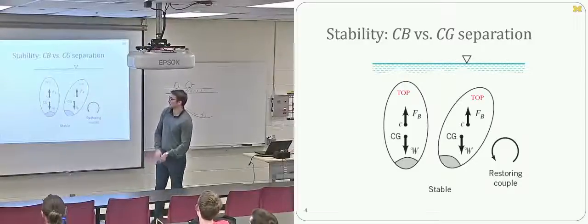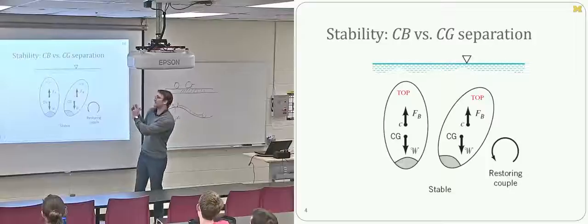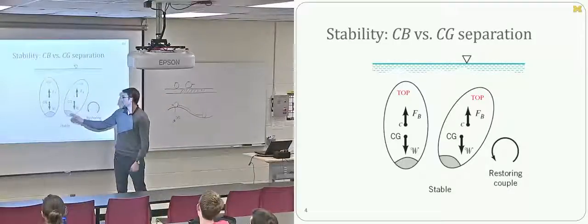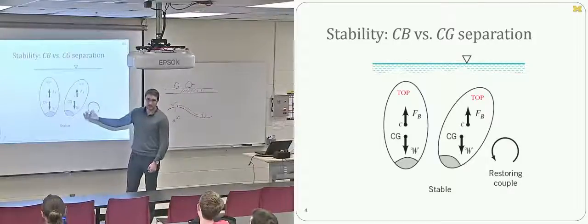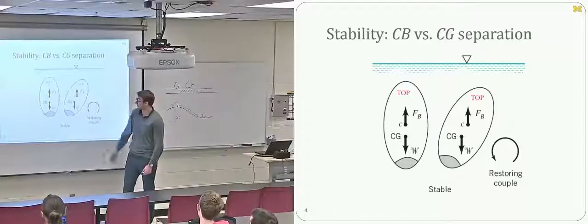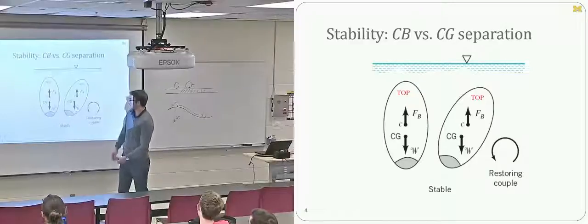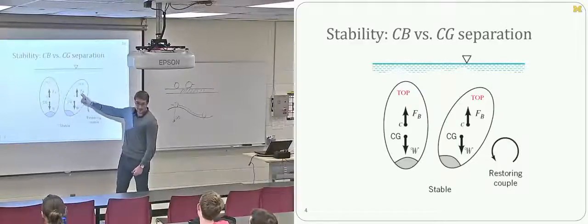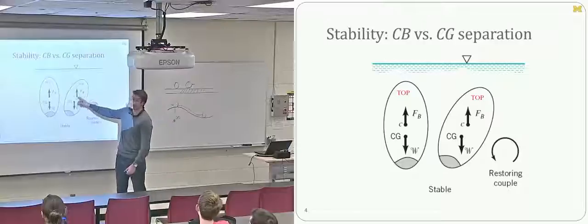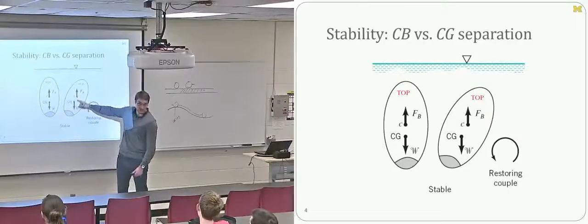The idea here being that, for example, if you took that ball of plastic that I was talking about earlier, and you attached a weight to the bottom, now the center of gravity is located below its geometric center, right? And so if it's at a stable condition and you perturb it, the center of gravity acts through the same position, and the center of buoyancy acts through the same position because the centroid of its volume doesn't change.